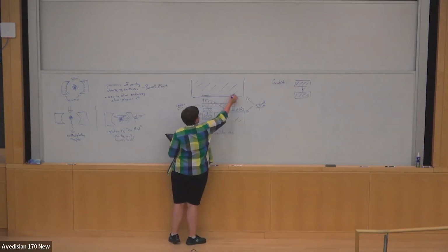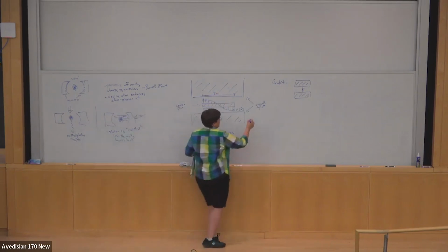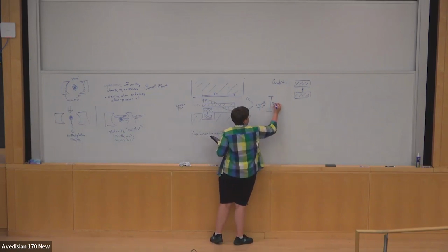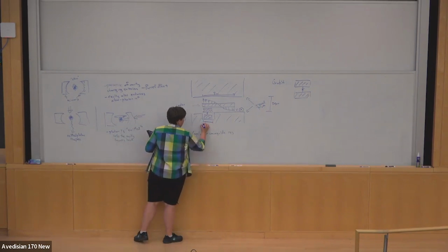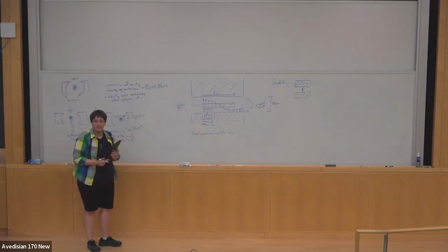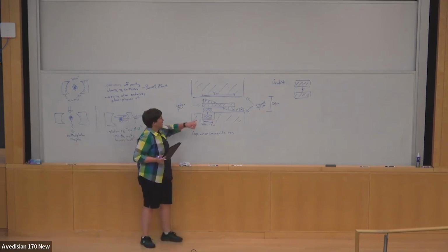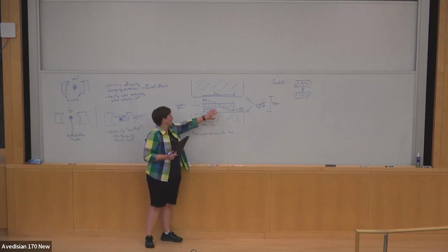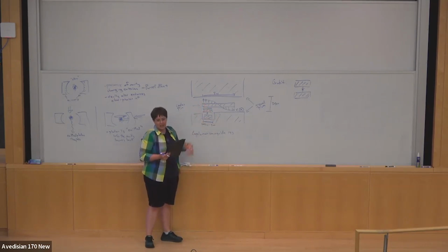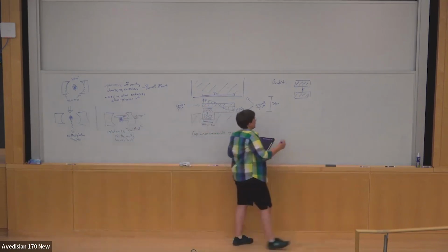Maybe a scale bar would be helpful. 8 millimeters long. Very much not to scale. I think for many people, this is 20 microns. And the qubit, 500 microns to 2 millimeters wide. They could be gigantic. So these are sort of roughly the scale. And so you put the qubit sort of counterintuitively not at the center of the cavity, because the center of the cavity actually has a voltage node there. So you don't get any coupling. And so the qubit's always going to be at the end of the cavity where the voltage is large. And so what are the advantages of this?